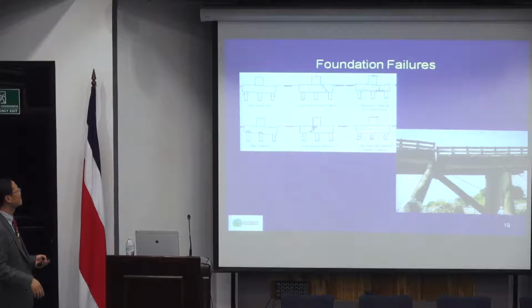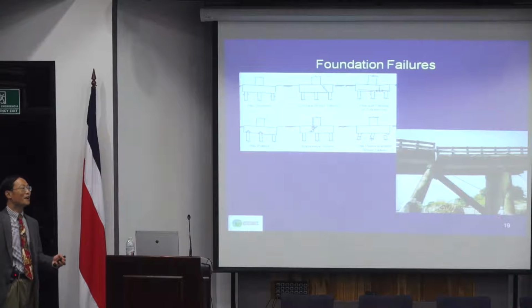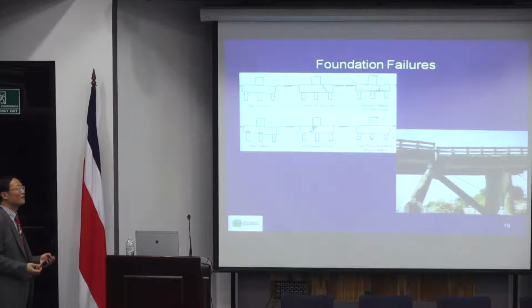It's just a crash, and sometimes it could be the pile cap fails, either shear failure or bending failure. But most failure is caused by the pile itself. And of course, there's also the possibility of a failure of these. But failure of these is typically due to lap splices. We just had a picture, and they just don't have enough lap reinforcement so that they're separated.